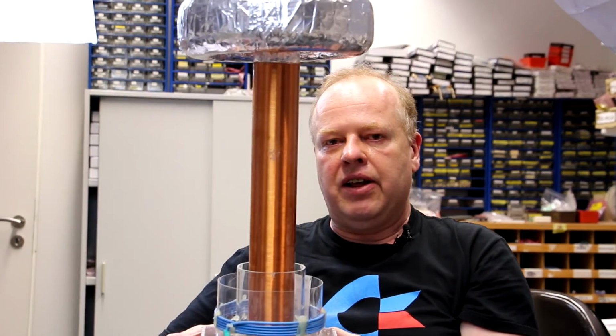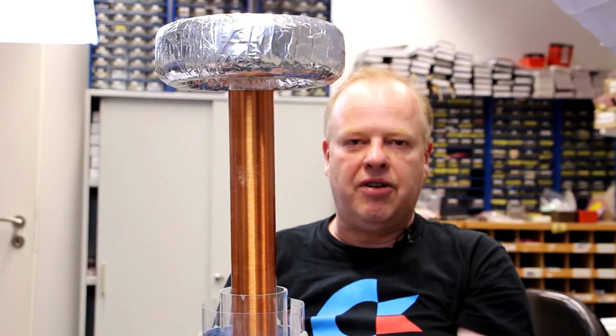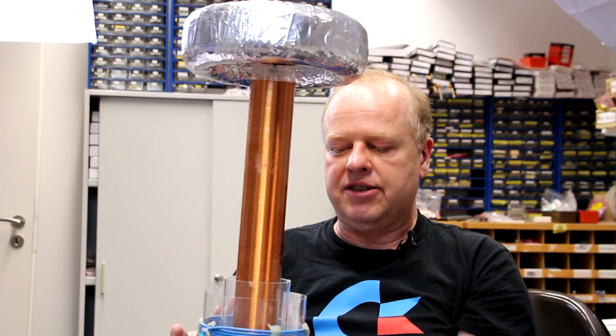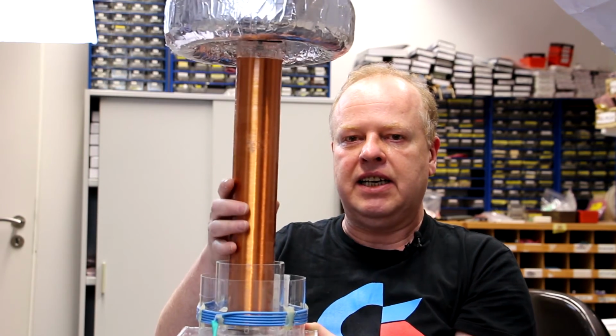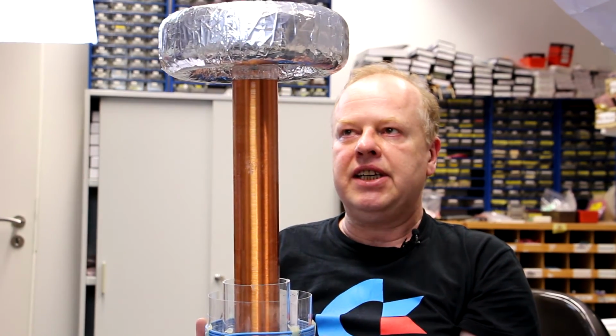smartphone or whatever. And you might have seen, or I'm sure you know what this is, a Tesla coil. This also depends on the principle of two coupled resonant circuits. You perhaps can see here the primary coil and the more prominent secondary coil. And in Tesla coils also not only the coupling but also the Q factor of the primary and secondary tank circuits are quite important concerning the efficiency.